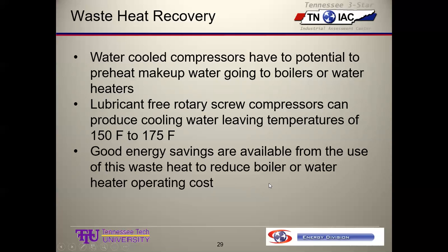The lubricant free rotary screw compressors typically have a Teflon type coating on the screws to do their best to minimize friction, but it's still not as good as spraying oil. So the lubricant free compressors won't be quite as efficient as the lube injected ones, and that extra inefficiency can generate some higher temperatures.